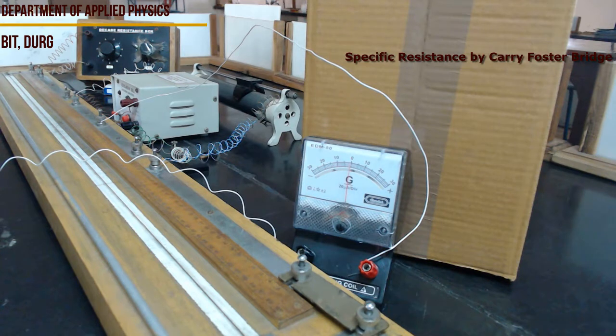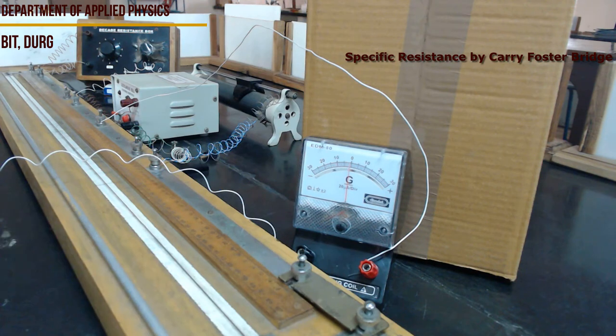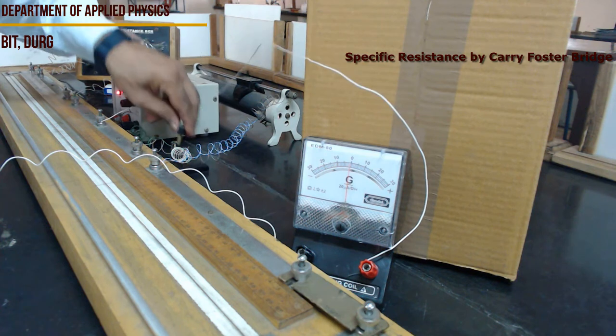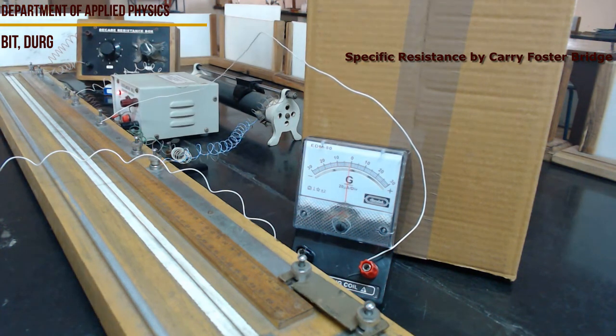Now the first step is, first of all, we keep the value of resistance in the resistance box equal to 0. This white dot corresponds to the 0 mark. 0 multiplied by 0.1, which is equal to 0. So this is 0, this is also approximately 0. Now what we do, we switch on the circuit by switching on this Leclanché cell and putting this key plug inside the one-way key, to switch on the circuit.